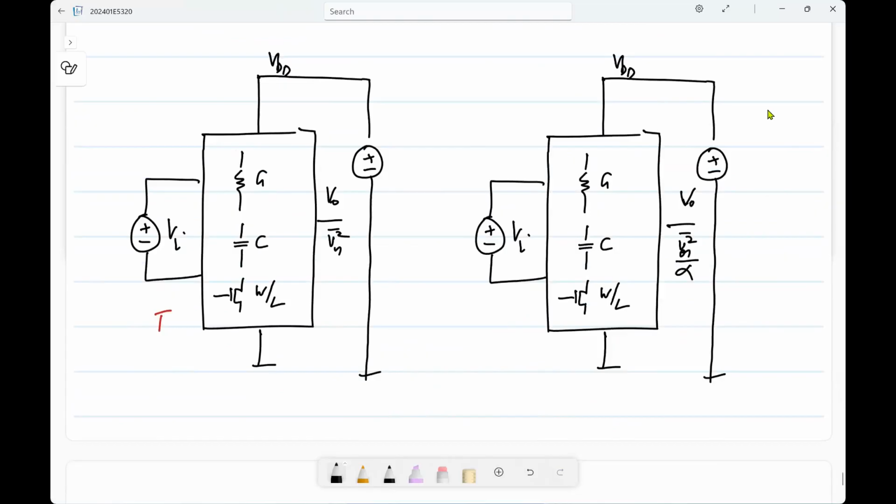That's what he said, no? This will cool the circuit, because every noise spectral density expression seems to have absolute temperature in it. So now to get the same result, to get a noise power of VON square by alpha, what should be the absolute temperature? What should be the absolute temperature? T by alpha.